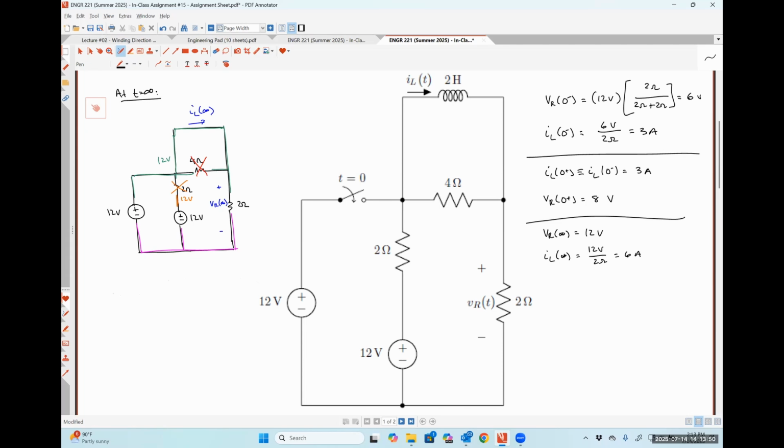Why is there no current flowing through the 2 ohm resistor? And it's got 12 volts on both sides. So what's the voltage drop? 12 minus 12 is 0. Yes, sir. I'm just double checking everything. So I have that one big top node and then the bottom node and then just that one smaller node between the 12 and the 2 ohm resistor. So I feel like that seems legit.